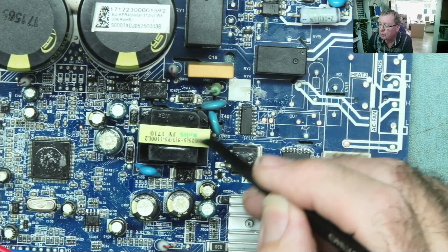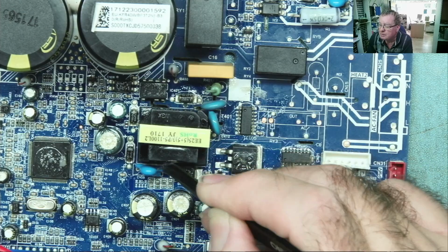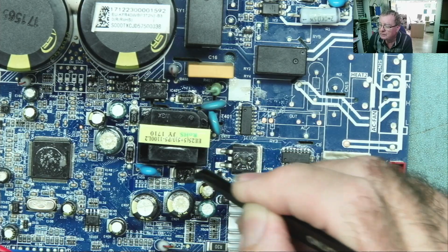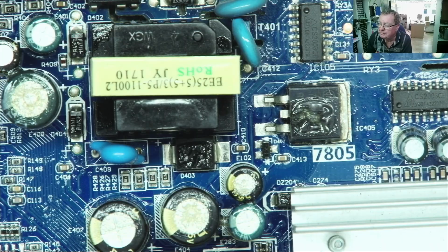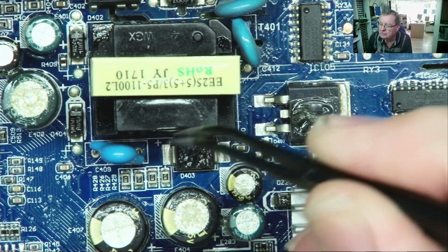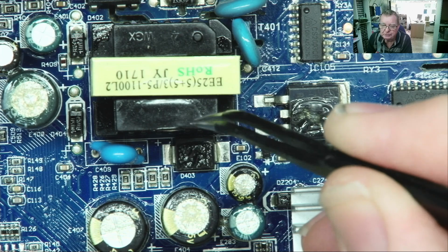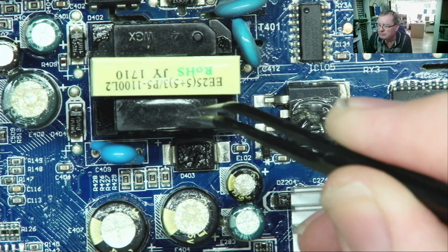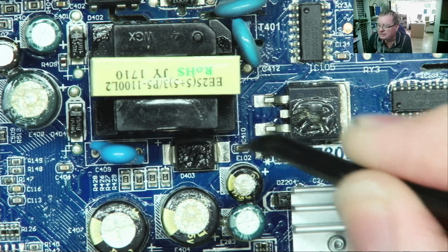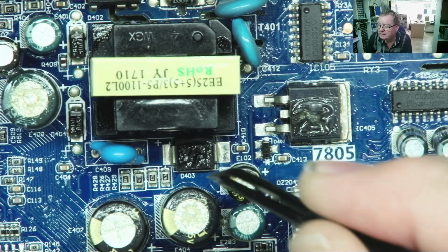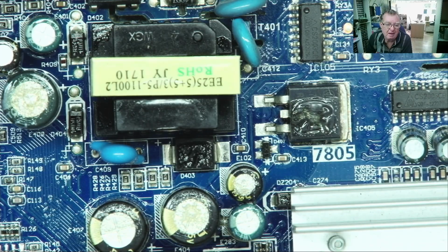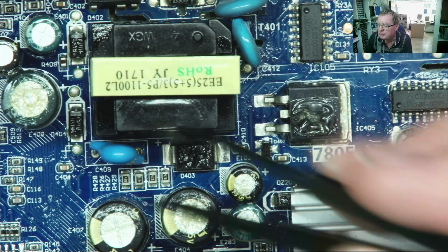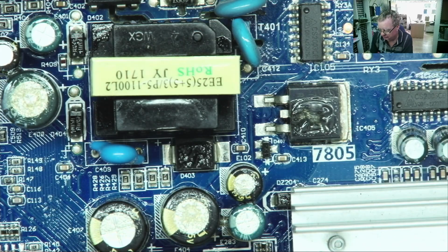And you will always find in these circuits on the output, this is the low voltage side, a diode like this. So this is the rectifier diode converting the low voltage AC, high frequency, coming out of the transformer into DC to be smoothed by the capacitors. These are a fairly common failure. Always worth a check on a switch mode like this is the diode short.